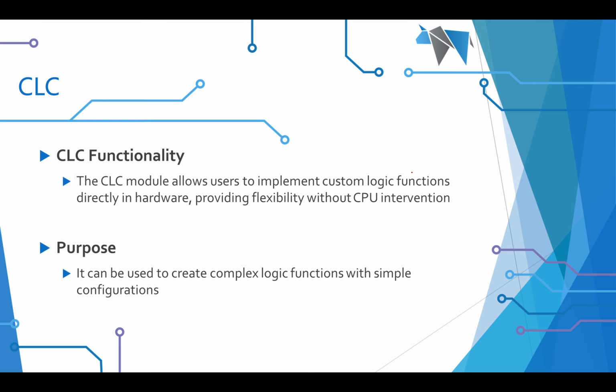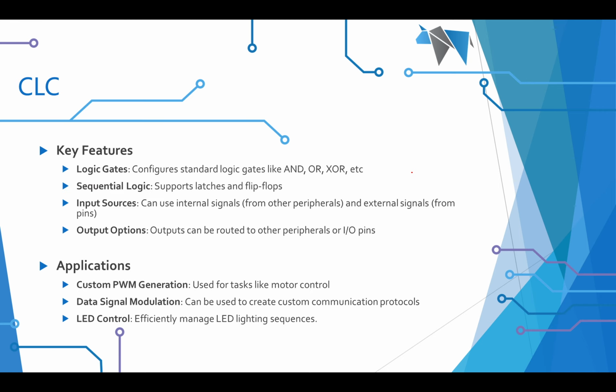So what it allows you to do is define custom logic functions in the hardware. There's no CPU intervention. This goes on all the time. There's no interrupts. It's just in the hardware. And you can create quite complex logic functions. You might want to use it because you can do ANDs, ORs, you can do flip-flops, sequential logic, different inputs. I'm going to have an input as a switch, but it could be a timer, external interrupt, etc. And the output can go to other parts of the microcontroller or back into another CLC.